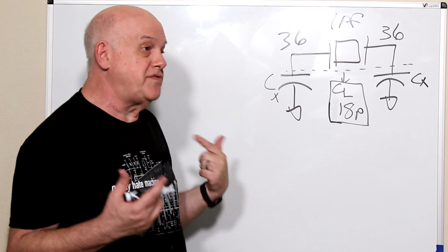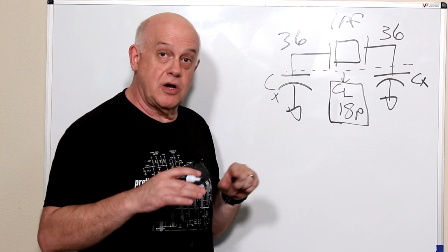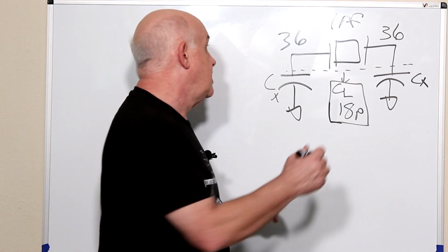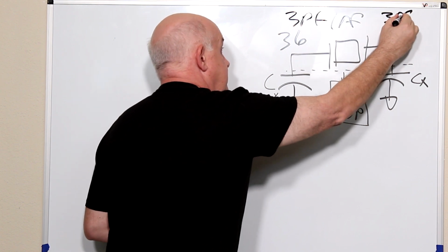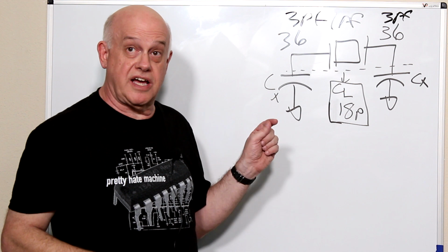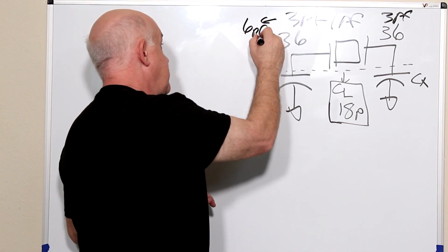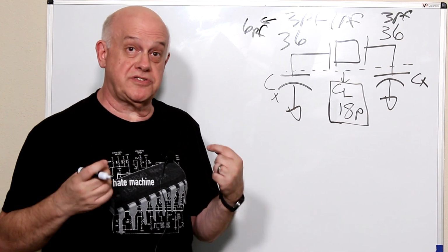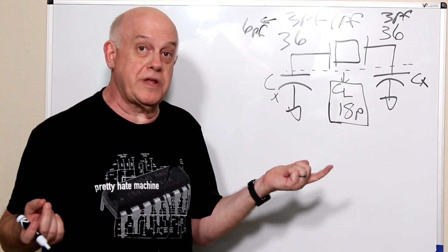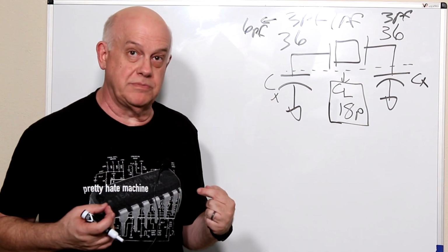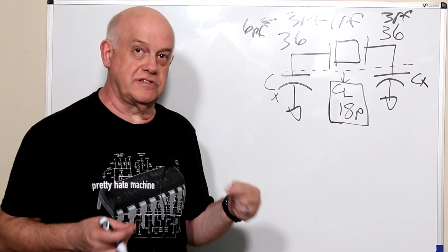My experience has shown the following. If you have a part that's soldered into the board, no socket, you can use about 3 picofarads for each pin. If it's in a socket, change that number to 6 picofarads. If you have it plugged into a solderless breadboard, it could be anything. I've seen stuff like 40 picofarads for an old, dirty solderless breadboard. Here's a pro tip. Don't try to run a crystal oscillator in a solderless breadboard.